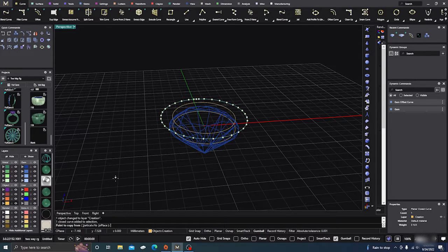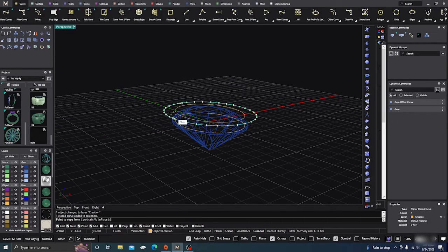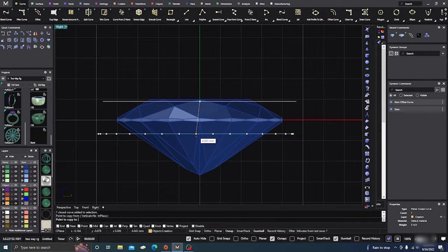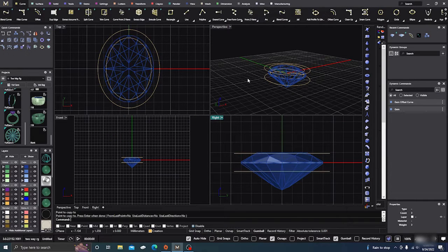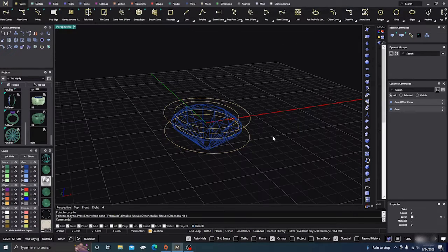And then from here, you can duplicate that again from your quad. Turn on snaps again. Make sure your quad snaps is checked. Go to quad, and then we'll go to the right view, and this particular one we want a little level out, so we're going to hold down shift, turn off our snaps, somewhere around here. Okay, now we have it going down, but we don't want it going down. We want it going out. We want a little bevel right there because we're going to add some stuff to it.